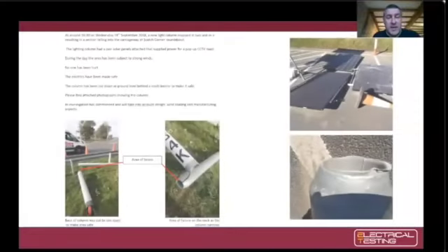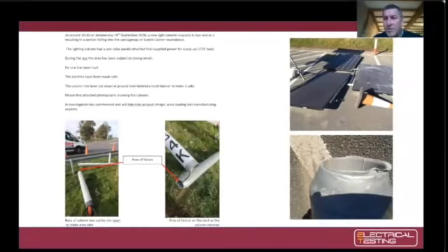This one I find fascinating in many respects, because a lot of the safety alerts that are brought to our attention, the columns are defective. There are evidence of corrosion or damage to the column. This is a newly installed column, so it's within a year or so old. It's been installed into a new scheme. It's not been approved for a solar panel, but a solar panel of approximately 1 meter by 2 meters has been installed on a fixed bracket.